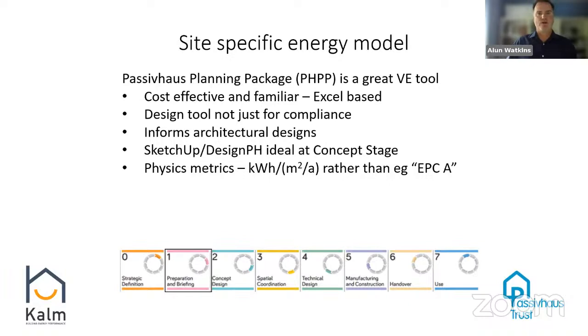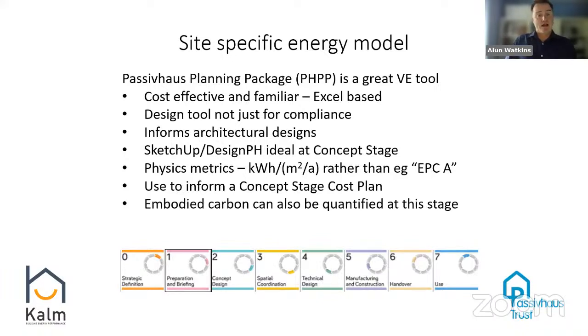So we're very much focusing on those physics metrics in our energy model, and it's quite quick then to convert this to a concept stage cost plan, and see what the budget's looking like from the outset. Embodied carbon can also be quantified at this stage. You're getting the quantities in early, and you can start to make those tweaks, which can potentially quantify embodied carbon.